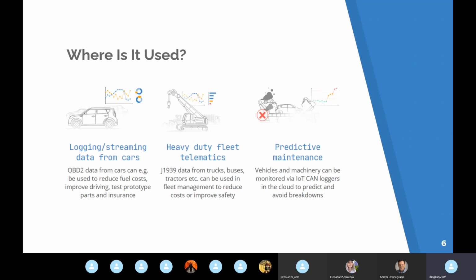I think it was in 1997 they made it standard on all cars mainly to track emissions data, and then in Canada they took that away sometime in the 2010s. In electric vehicles, most of them don't need to have normal OBD2 ports because they don't have emissions. OBD2 is a form of CAN. It's a higher up layer of CAN, but it is using the CAN network inside to access the data.